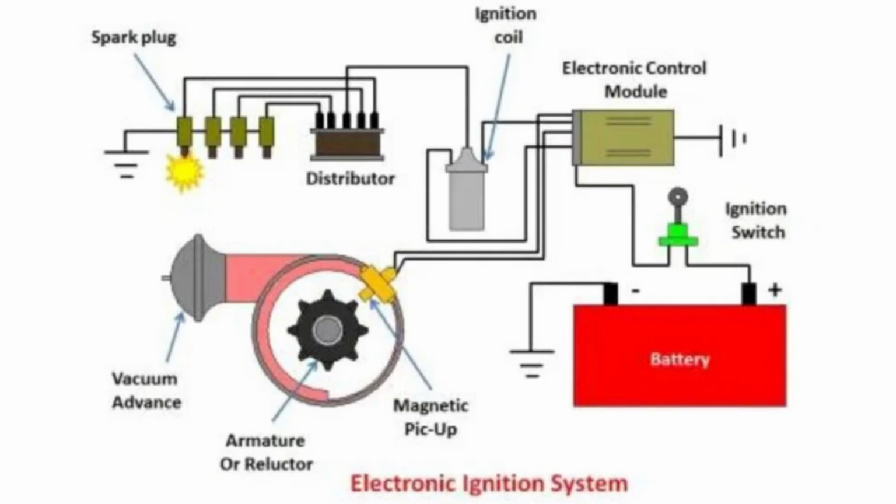Modern ignition systems. In modern systems, the distributor is not used and ignition is preferably controlled electronically. Small coils are being used with a single coil per spark plug. These coils may be mounted remotely or installed on top of the spark plug, which is known as direct ignition, where one coil works for two spark plugs, that is, two cylinders.